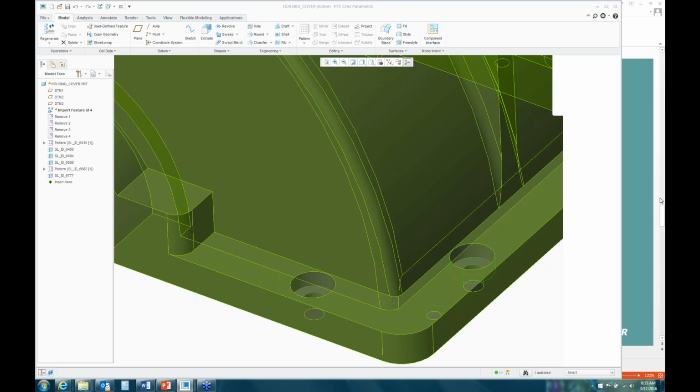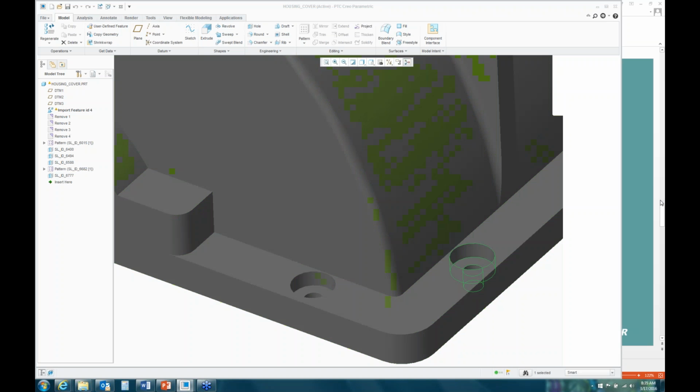The next question is, can we talk about the change in the design flow for using IFX? For instance, we already had an axis created for all our fastener locations. Well, as you saw during the demonstration, I showed how to create the fasteners on a mouse pick. So you don't necessarily need to have those locations predefined. It certainly works a lot easier to have those positions, but it's just a little bit more work after the fact to do the mouse pick and then pattern that afterwards.